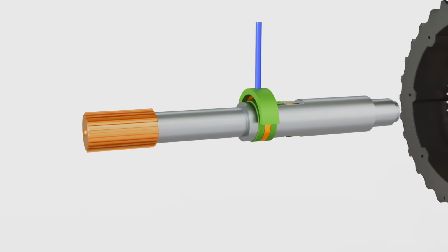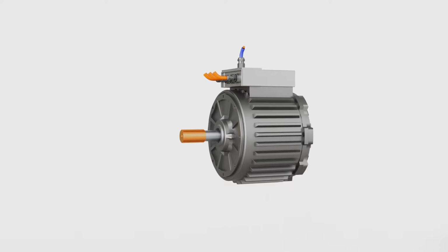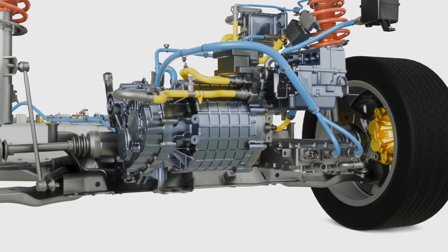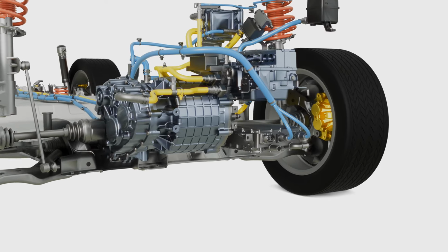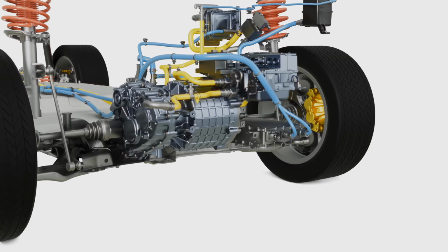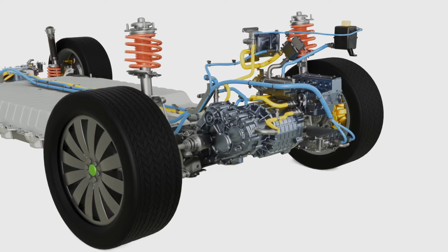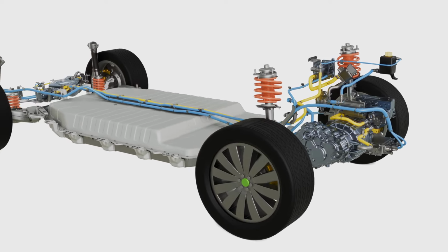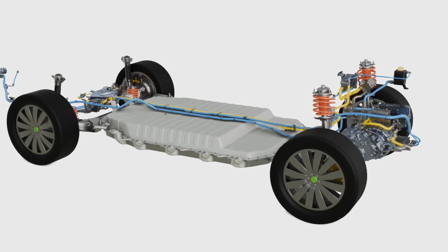In any powertrain design, cost is a critical factor. Any additional component will add to cost. But with this improved direct torque control technology, we can potentially reduce the overall cost of the system. We have removed the requirement for the costly sine-cosine position sensor. Because the algorithm is much simpler to execute, we've been able to reduce the need for processing power. This opens the door to lower cost microcontrollers, which are always going to be a significant part of the control system bill of materials.